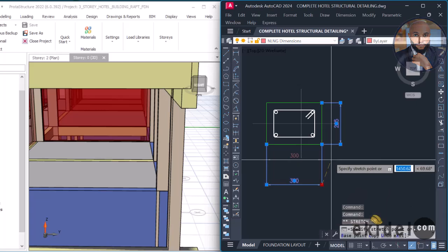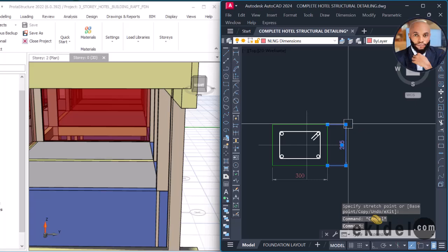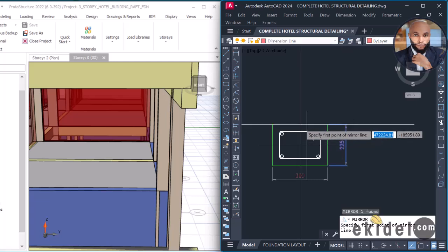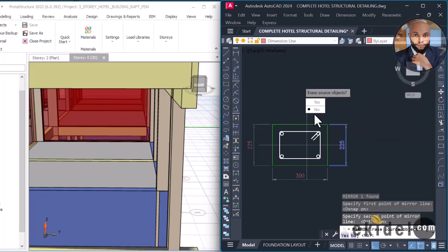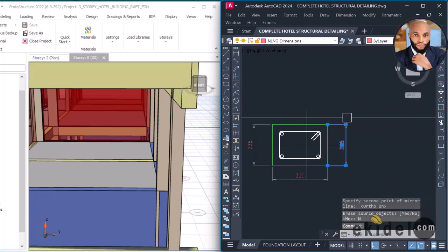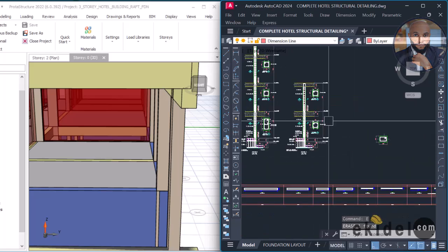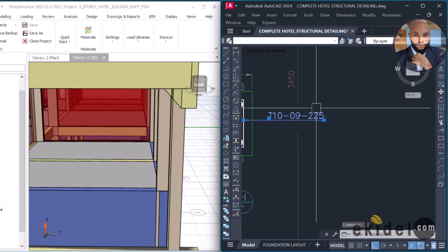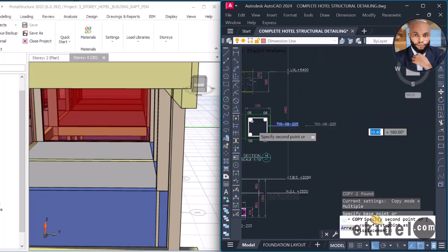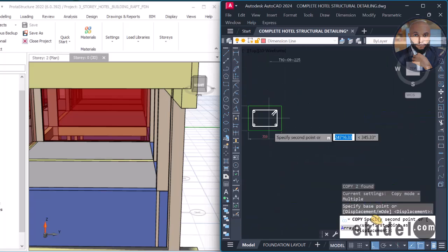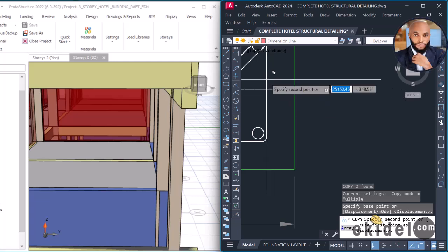Okay, that's fine. And then I will now mirror this backward from the center line here. Mirror this. Okay, that's fine, and say no, then take this off. And then by doing this, I will come here and copy this, knowing that my spacing for that is 225 for my link spacing, and I'm using diameter 10. I'll keep this here, and keep this here, and keep this here, just here.